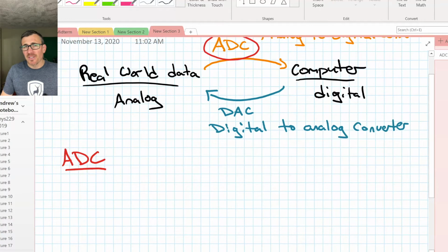So somehow we have to take our continuous voltages and turn them into bits. Now there's a number of different technologies that exist for analog to digital conversion, but we know how to build them. In fact, using the black boxes we've already understood in this course, we can completely understand what an ADC does or how to build one. So let's make a fairly simple one, a single slope ADC as it's called, out of the stuff we've already analyzed in the course.